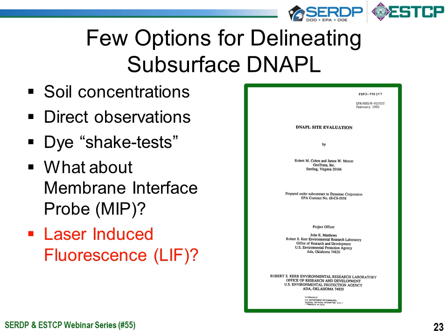Laser-induced fluorescence, on the other hand, only detects NAPL, if it's present or not. And until now, you have to rely on the innate fluorescence of the NAPL. There has to be PAHs, polynuclear aromatic hydrocarbon compounds, in the NAPL that will naturally fluoresce if they're bombarded with a certain spectrum of light. And that's the whole premise behind laser-induced fluorescence.